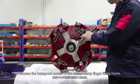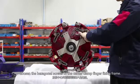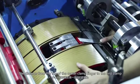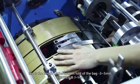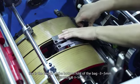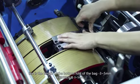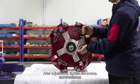Loosen the hexagonal screws of the center clamp finger fixing frame. The distance from the top of the center clamp finger to the first clamp line is the length of the bottom fold of the bag minus 3 to 5 mm. After adjustment, tighten the screws.